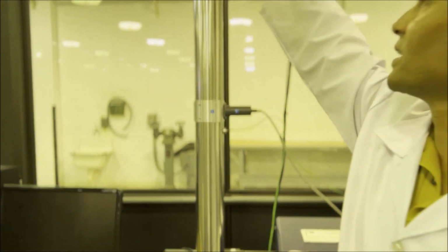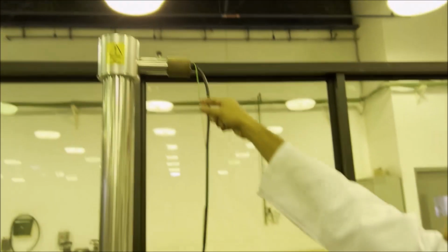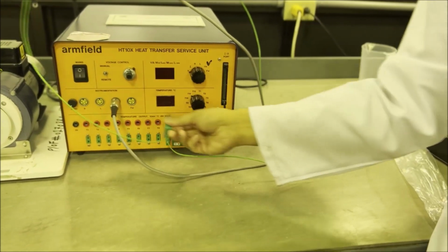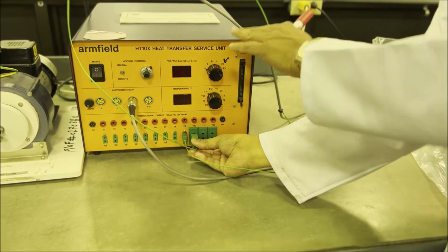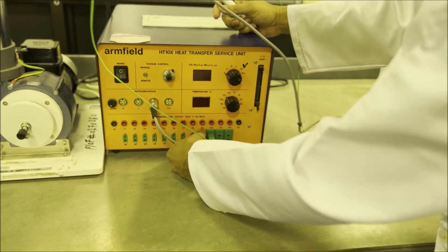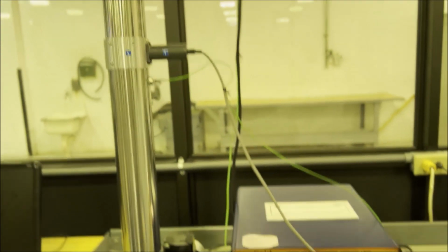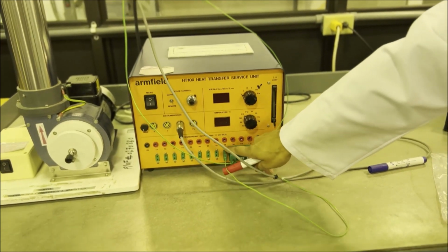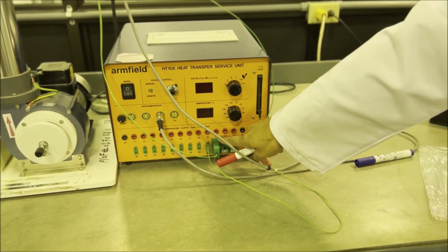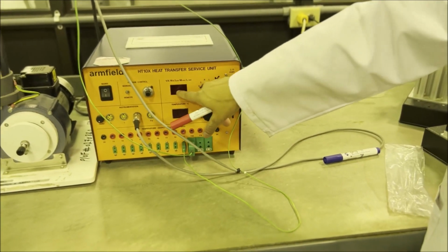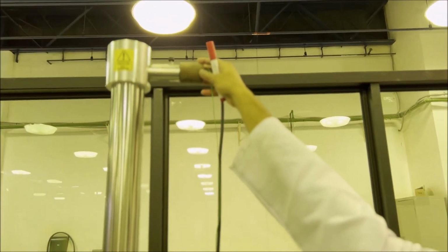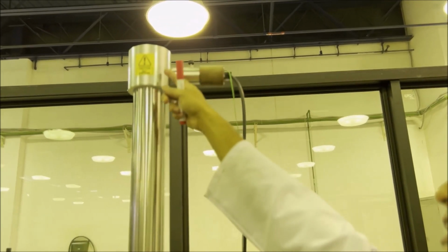Here we can measure the velocity, but for natural convection there is no need for velocity. Here we need to measure the surface temperature of the rod using this thermocouple, which is connected to 10 because of the big socket. There is another thermocouple here which will measure the atmospheric temperature, connected to 9, so I need to measure T9 and T10. Then I need to measure the voltage and current given to this heater, so that I can find the heat flowing outside.